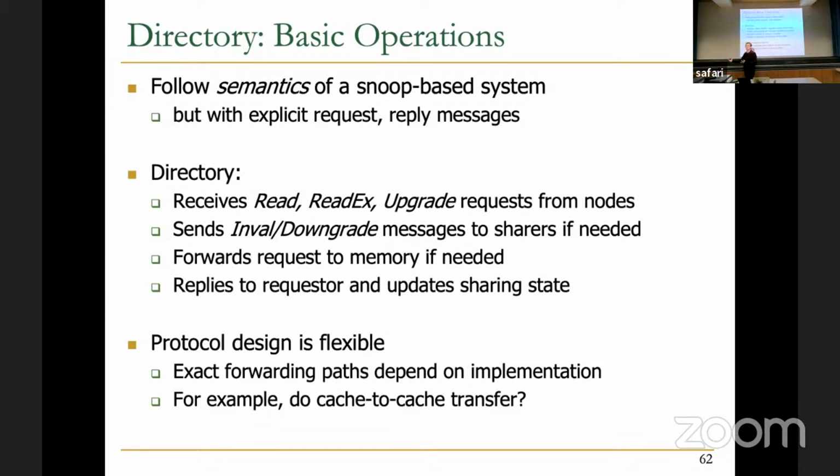Whereas it's much more difficult to do that with a snoopy bus-based protocol, because you're really relying on broadcast messages. First of all, you don't have a whole lot of options. And second of all, you need to bake those things into hardware. The fact that you have a mediator enables you to make that mediator intelligent. Now that directory is part of the memory controller, it can actually have some program running to serve these requests, right?